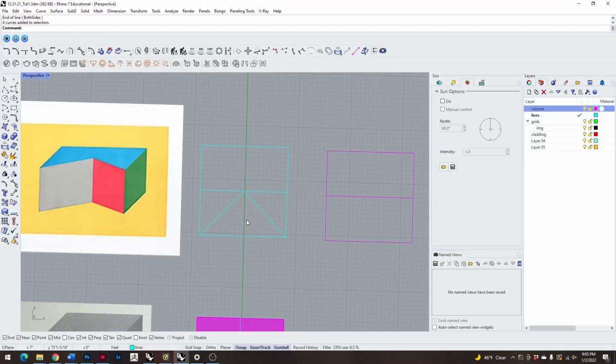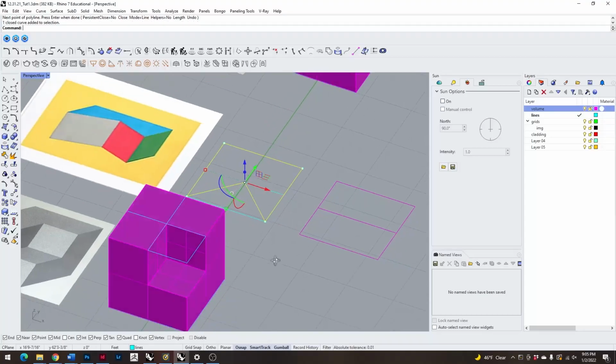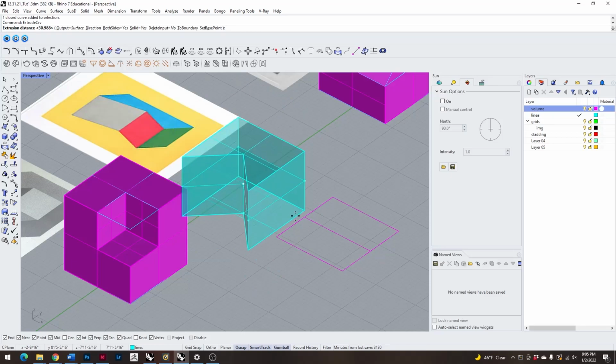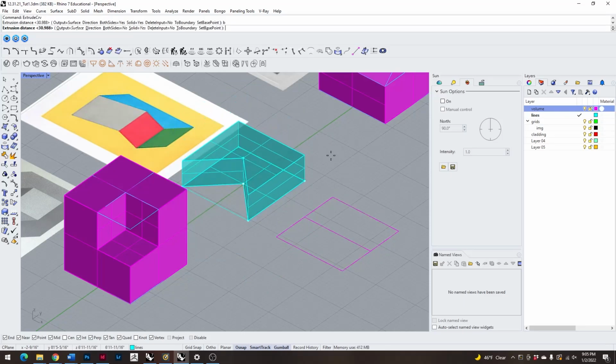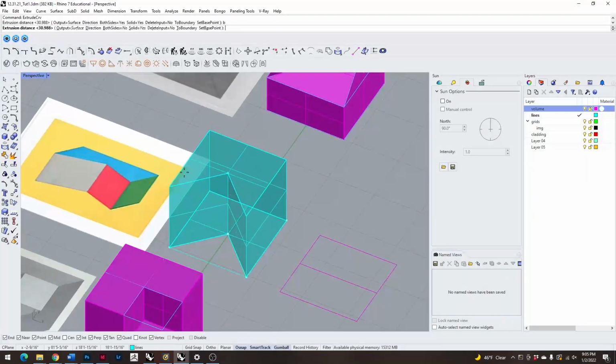And so there's a couple ways of making this curve unified so that we can extrude it. The first would be to do a polyline and then connect all the different points that we want. Select that line and then extrude this curve. We don't want both sides on in this case, so we'll toggle that off. And then we'll lift it.